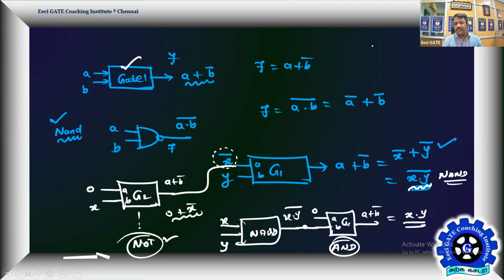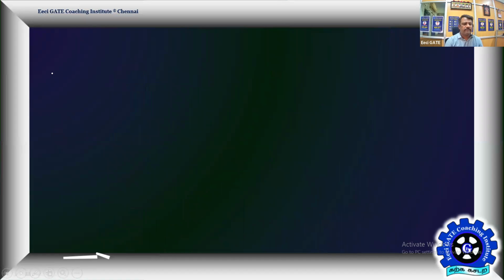So you proved it is implementing AND and it is implementing an inverter. You have to prove only that it is also producing the OR logic function. Then it is universal. Then you can click all the options, because all are proper logic functions that can be implemented by using this universal logic function given as A plus B bar. Now I need to prove myself again that it is possible to implement OR logic as well. OR means the function has to be A or B. Let me take X and this is Y. I want to implement this.